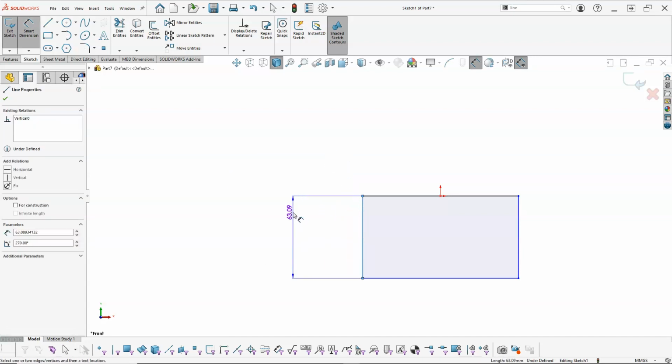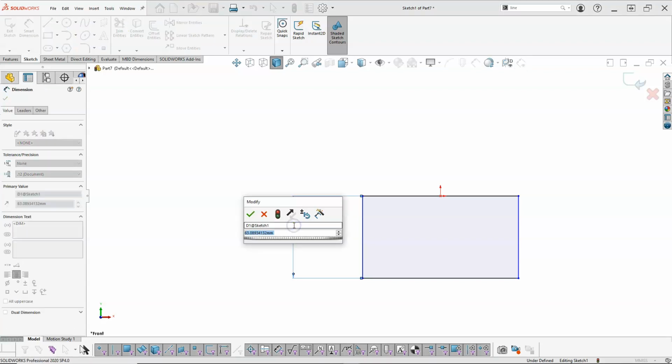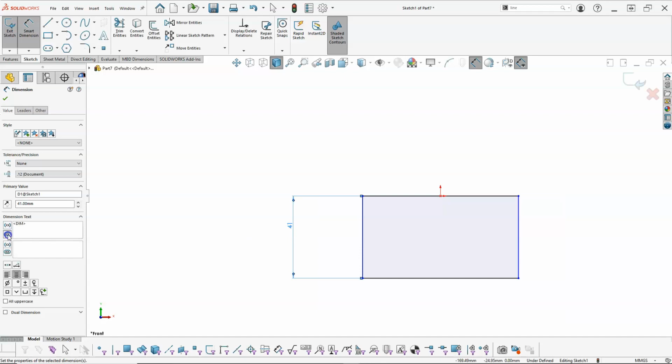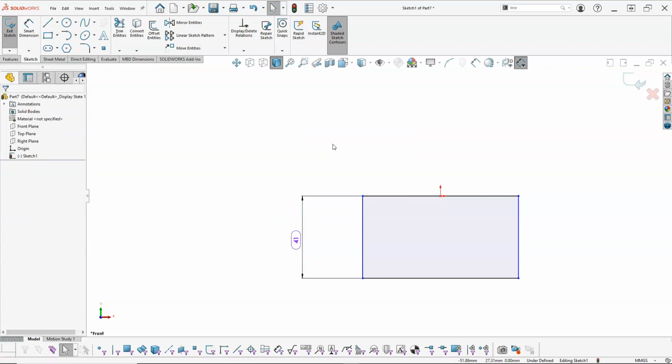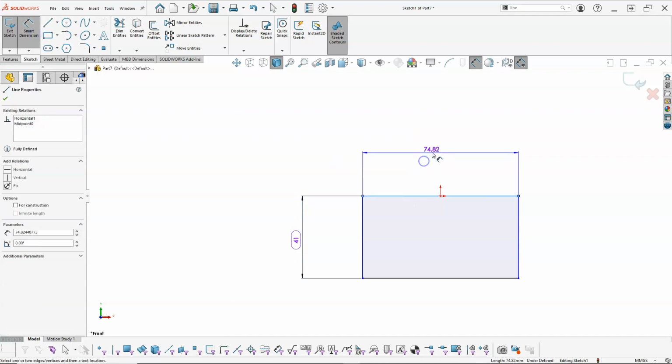Oh, we said we were going to mirror this, but I already jumped into one of those. Well, we'll use the symmetry. All right, so the height. It looks like we're missing a dimension. 21 and 10 would be 31, and then the height looks like about another 10. So I'm going to go 41, but since that one's a questionable, missing dimension, I can treat that as an inspection dimension or place the ob round on it, to be able to come back and check. Smart dimension is 60.